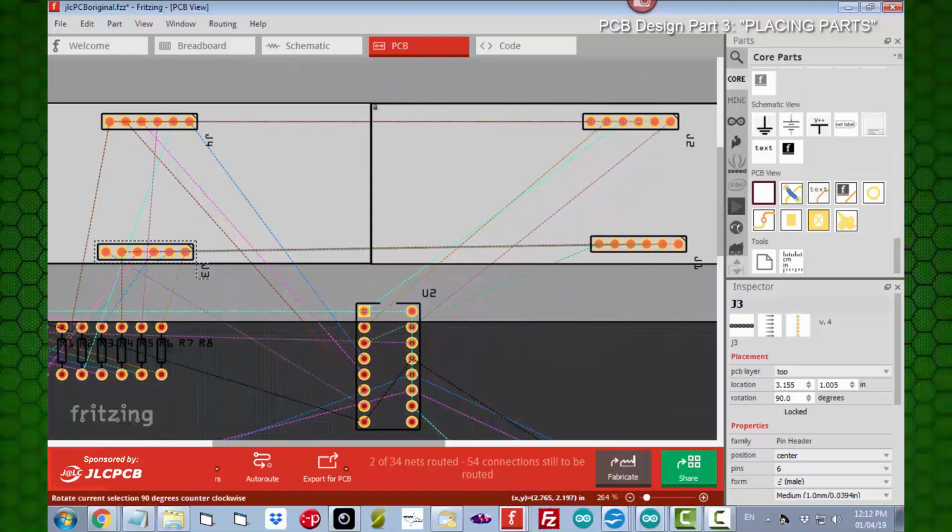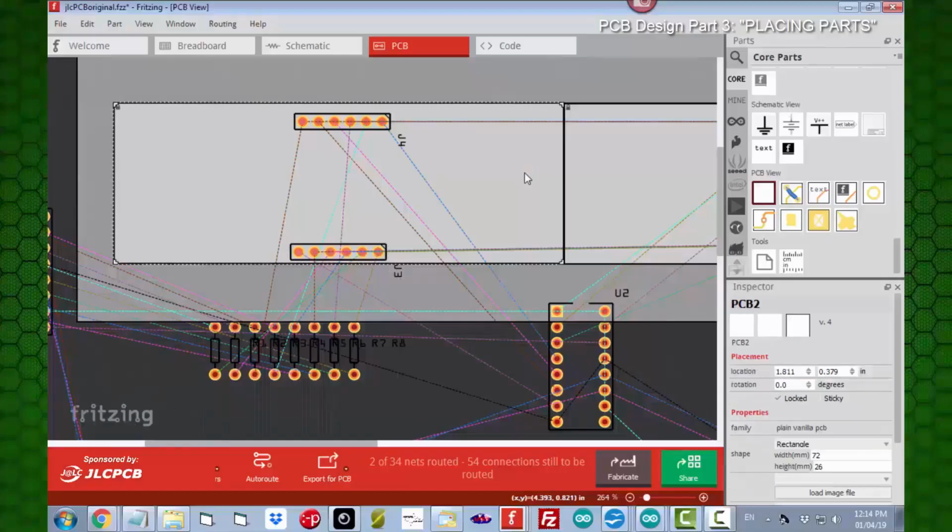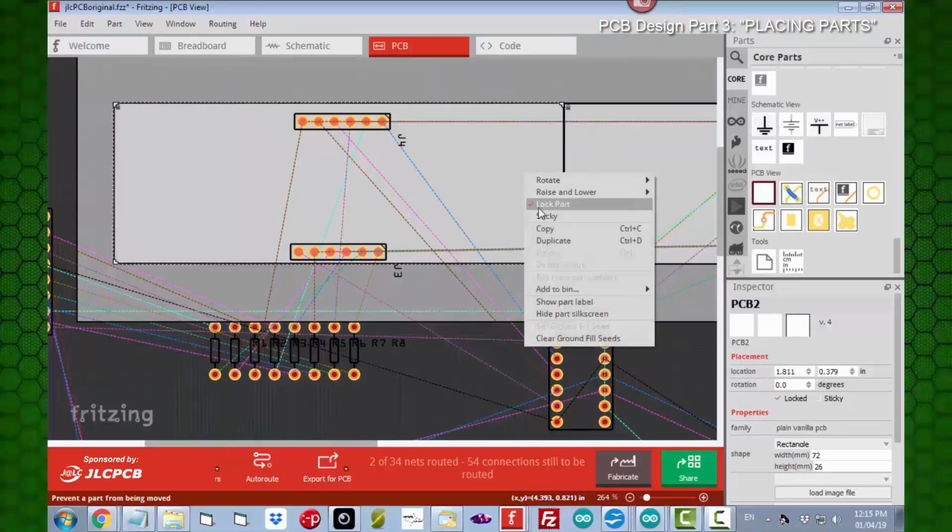This is how I'm creating the mirror image of our breadboard. Okay, so that's that part. The next challenge is getting those pins in the right position for our displays. And we'll do some more trick geometry to accomplish that. Watch this. I'm going to mess around with the size of this dummy panel again. In order to do that, I have to first unlock it.